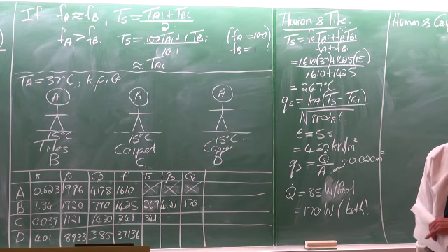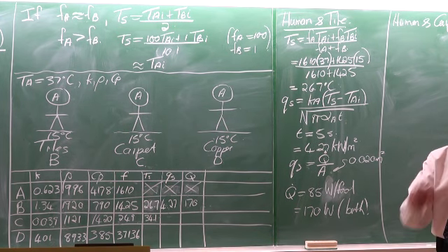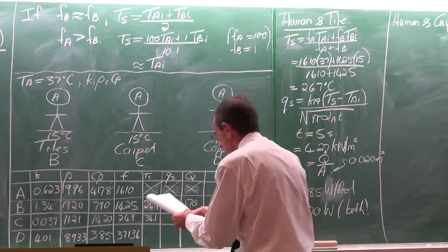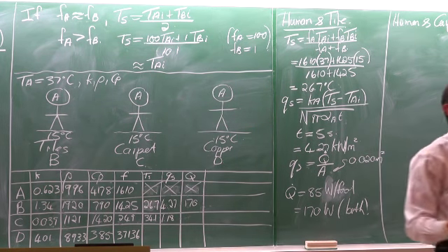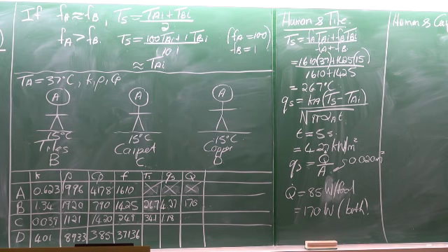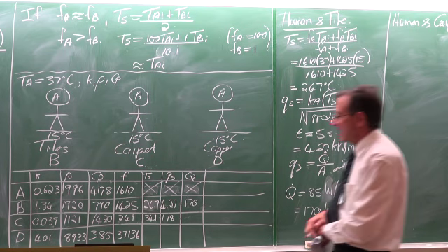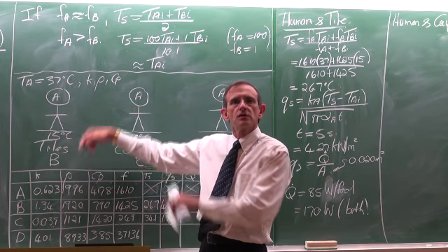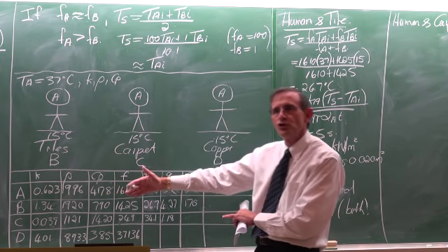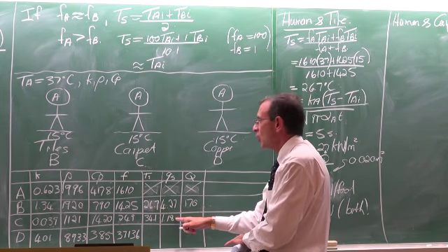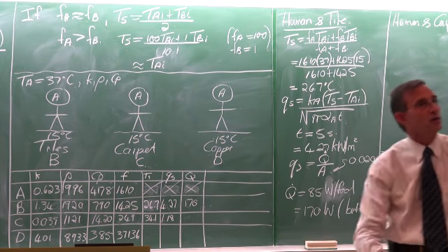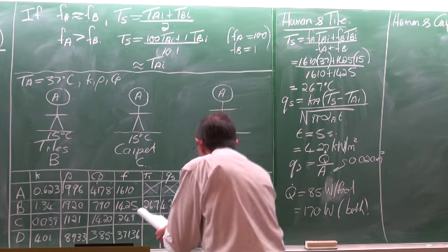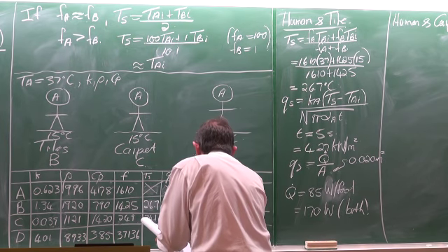If I can just give you a few seconds to correct what you should have corrected. Are you all with me? And then the heat transfer rate is only going to be 1.18 kilowatts per square meter. What does it mean? It means that if you walk over the tiles, the heat transfer rate is 4.27 kilowatts per square meter. When you walk over the carpet, it is just 1.18. So it's almost 4 times lower, the heat which goes out of your body. And the total heat transfer rate would be 47.2.